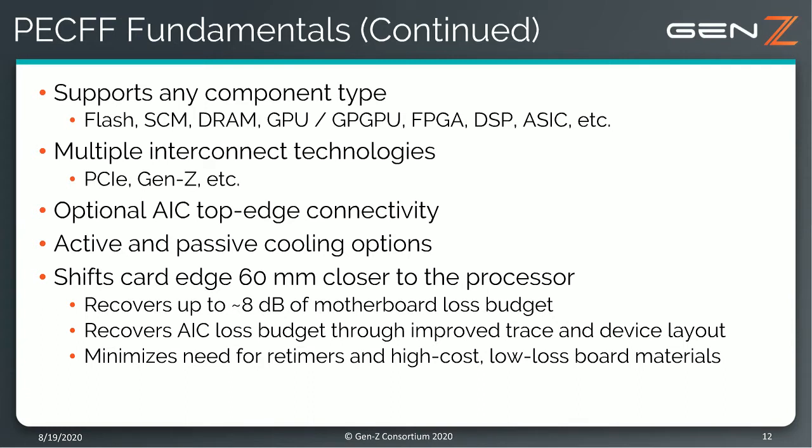This provides some SI benefits, recovering up to 8 dB of loss on the motherboard, and we also see improved performance on the AIC because the trace lengths are shortened and device layout is optimized. These SI improvements minimize the need for retimers and high-cost, low-loss board materials within the AIC and also within the motherboard.